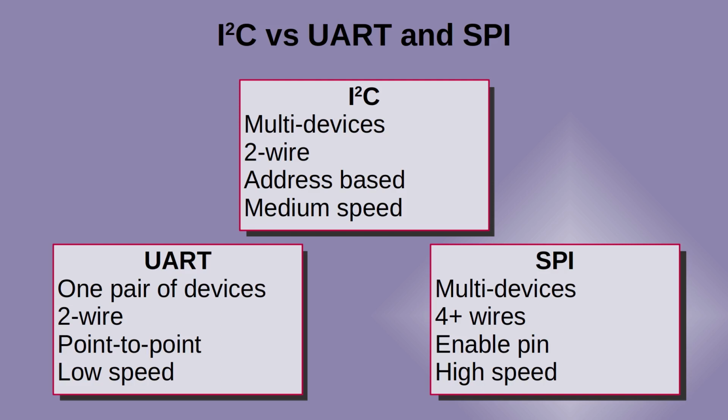The one thing I haven't listed is distance between the devices. This is because it can depend upon a number of different factors, and for most intended purposes of around 10 meters or less, then all 3 can be used. For UART and SPI, then 10 meters or more is fairly typical, whereas for I2C the official guidance is about 2 meters. However, with I2C it should be possible to achieve distance of 10 meters by running at a lower speed. The final thing I'll mention at this point is that the choice between SPI and I2C may also depend upon what other devices you want to connect to.